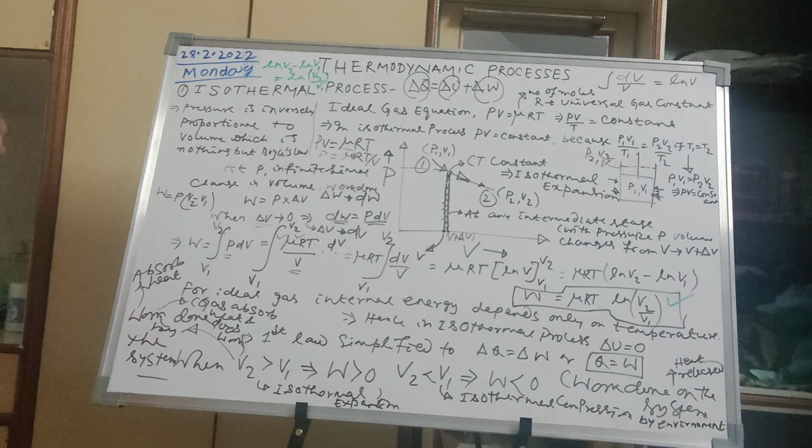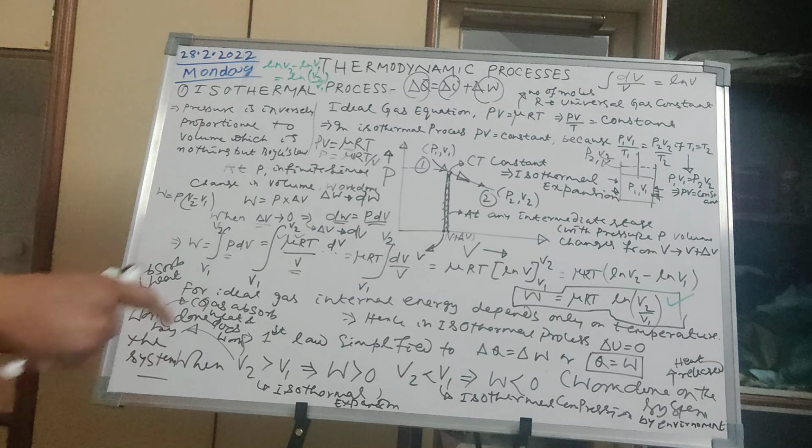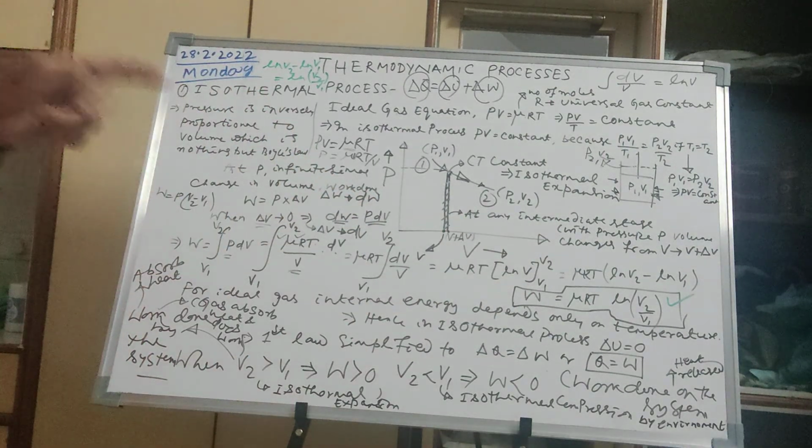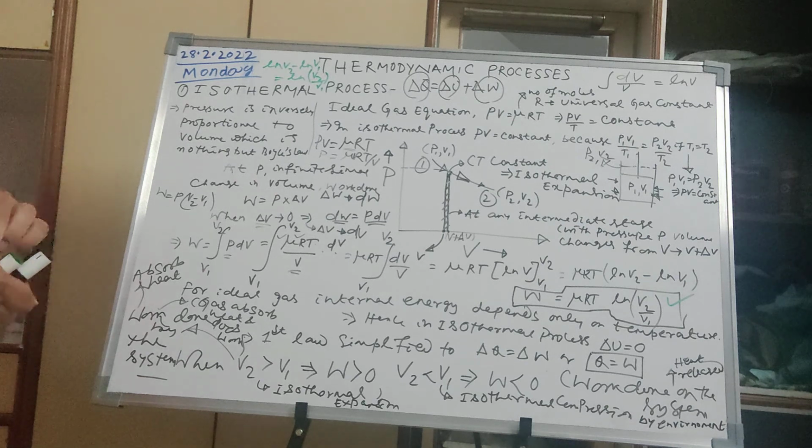And the heat input, you already know, is my calorific value. Let us say I am using 1 liter of petrol. For 1 liter of petrol, I know the calorific value, so there is nothing to calculate there. You can convert the calorific value into joule, and that becomes the heat input. But work done, you have to calculate. Only if you calculate the work done can you calculate the efficiency. So the whole intention of finding the work done is to calculate the efficiency, and the higher the efficiency, the better it is for you.